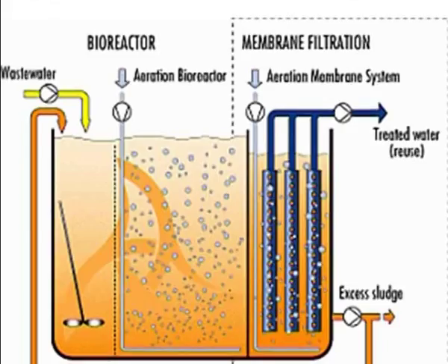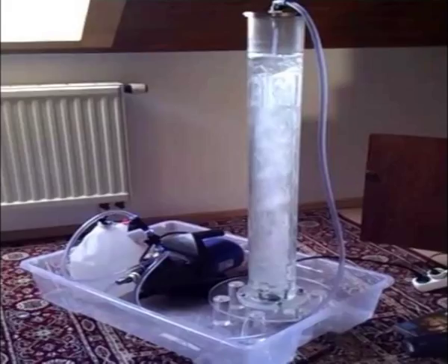In fact, to complete the treatment of the food processing wastewaters, the waste stream must be further processed by biological means. After adequate primary treatment, frequently used biological treatment systems include anaerobic processes, extended aeration, aerated lagoons, trickling filters and land application. Recently, some new highly effective processes such as membrane bioreactors and jet loop reactors have come into operation.